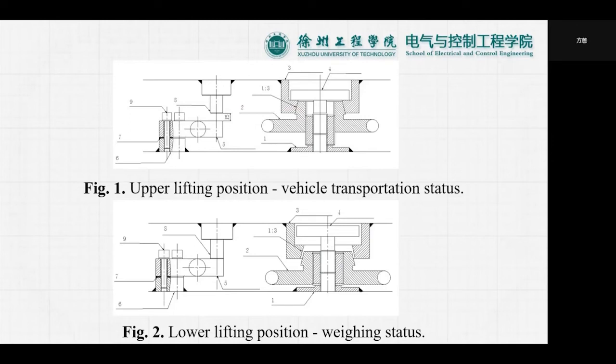There is no gap between the tapered shaft and the tapered hole, and the automatic alignment can be realized. The lifting thread is self-locking under the action of the vertical downward force of the weight, and the thread lifting thrust is significant when the lifting hardware is rotated.